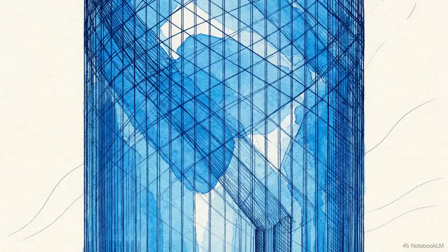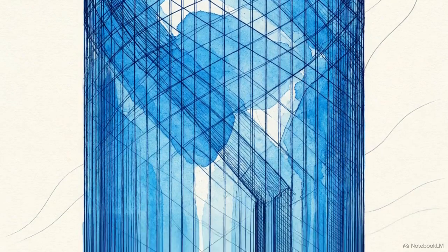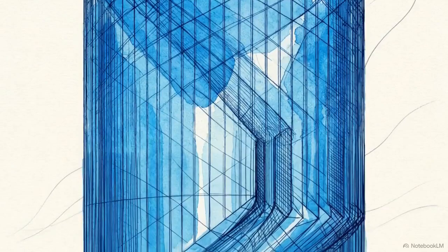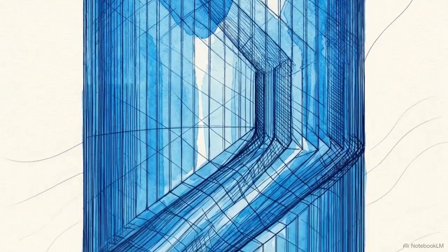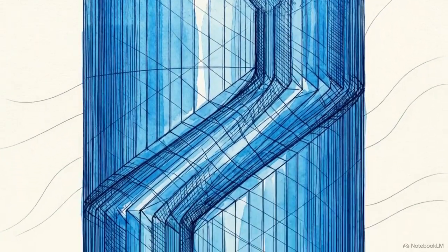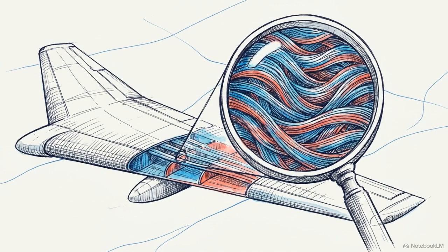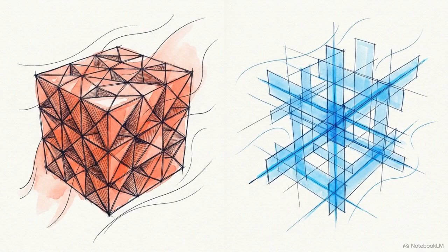When longitudinal compression is applied, the shell beam elements accurately buckle and shear, correctly replicating the localized formation of the structural kink band. By eliminating the computational bottleneck, engineers can simulate RVEs containing thousands of fibers, directly bridging the gap between microscopic manufacturing defects and macroscopic material failure. Simulating realistic composite failure no longer requires brute force computational power. It relies on an elegant mathematical abstraction scaling to meet the reality of the material.